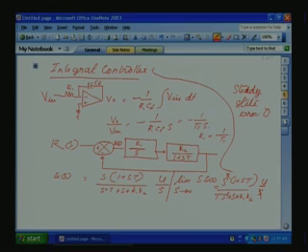But there is a disadvantage with this one. Sometimes it can create problems. When? See, we have only talked about the first order plant. So, the first order plant, if you see here, the signal comes to the feedback, so it is going through a first order lag. So, if you consider Rs contains various signals, it can be split into various frequency components. So, Rs with some frequency variation can give a phase delay here also.